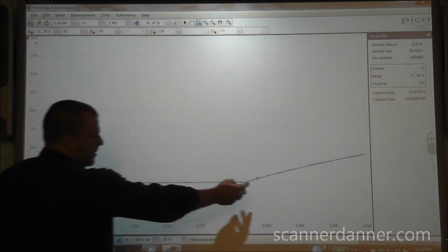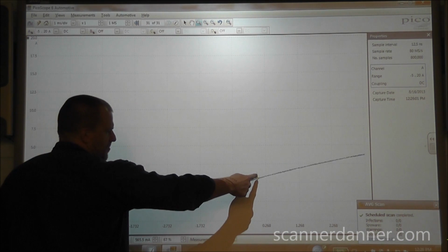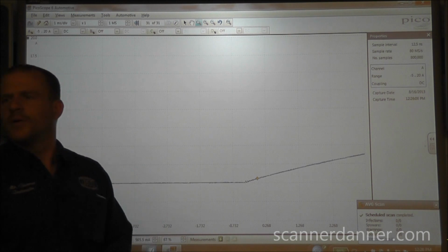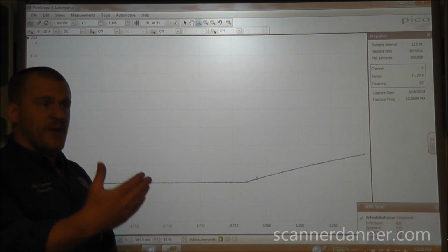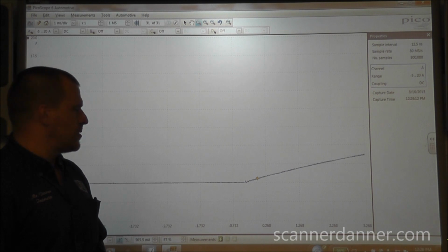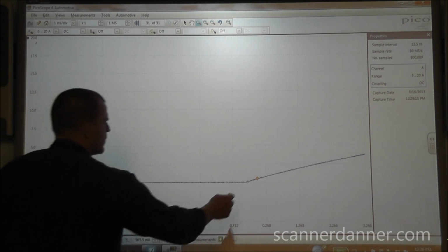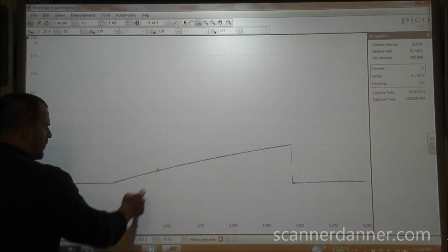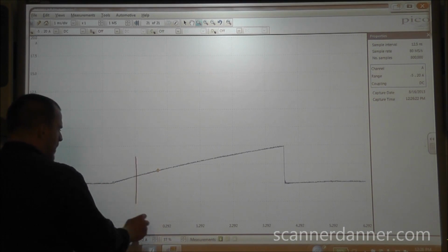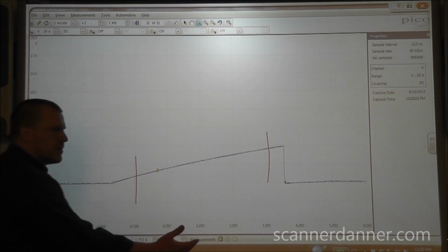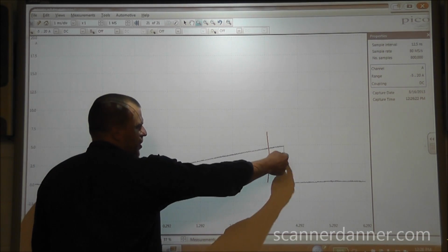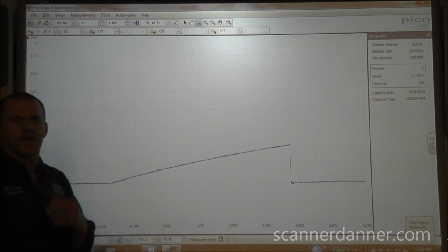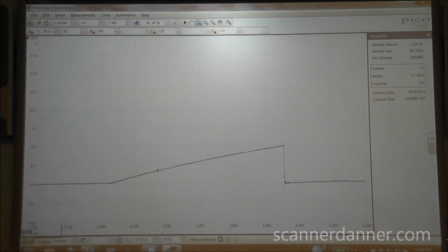So what's going on there? There's a rising edge on the other side. At that same level, there's a rising edge here. So when we set a trigger level, what do we want to do? Move it away from repeating, oscillating patterns. And so what we would do in this case, if we want a rising edge, let's move it over, and let's be somewhere in this area, right? Or maybe a trailing edge over here where it's nice and smooth up in this area. It's really going to depend on what you're working on and where you set that. All right, shut that off.